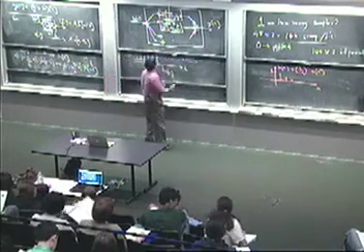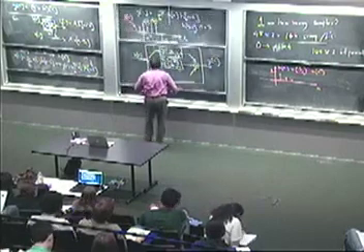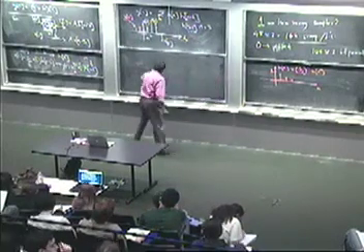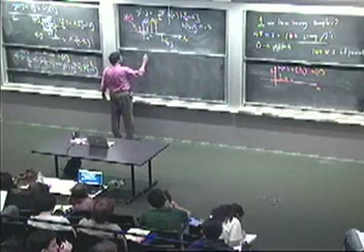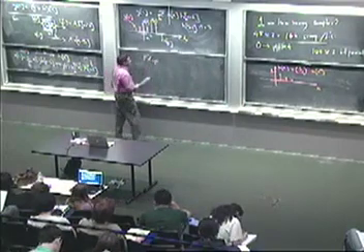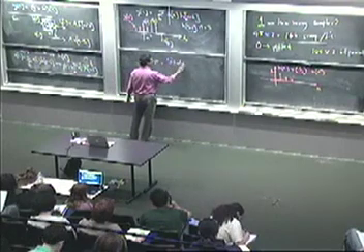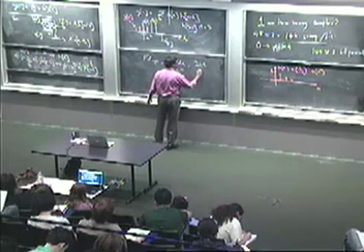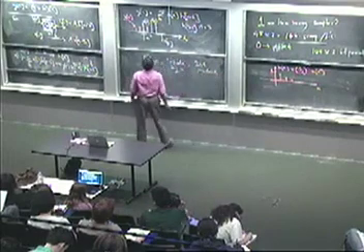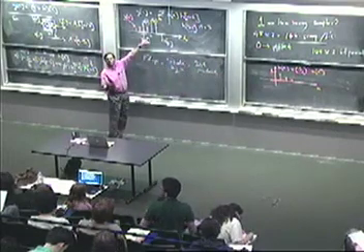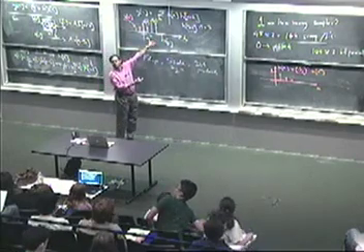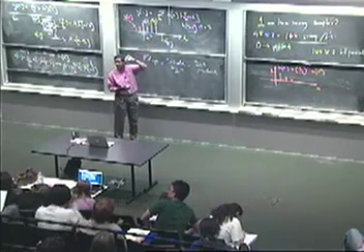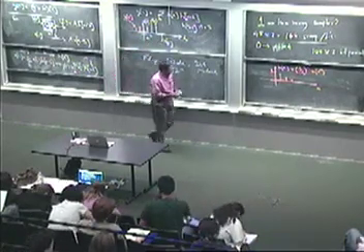All right, so in recitation tomorrow, you'll get practice on this. What you want to think of, sort of the mantra for graphical implementation of convolution, is you've got to do the flip of one of the time functions, slide by n, and then the dot product. Okay? So you slide it to get one particular value of n. If you want the next value of n, you slide it 1 over and go through this whole thing. So it's flipping, sliding by the right number of spots, doing the inner product. That gives you one value of the answer. And then you repeat. All right, you'll get more practice in recitation.